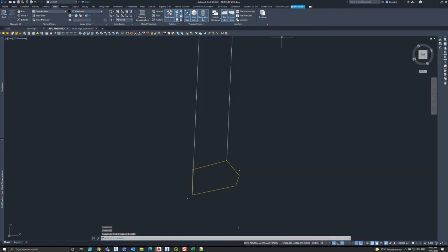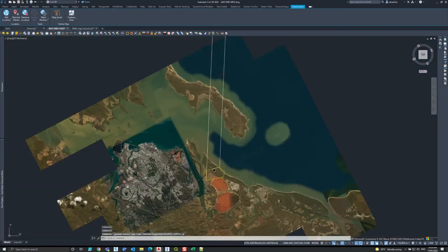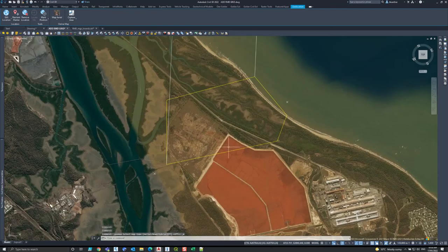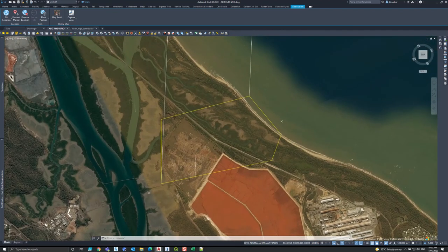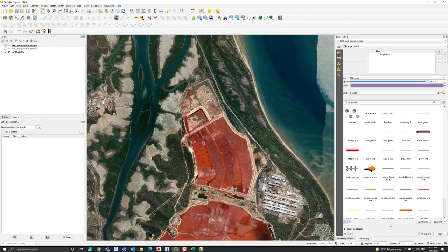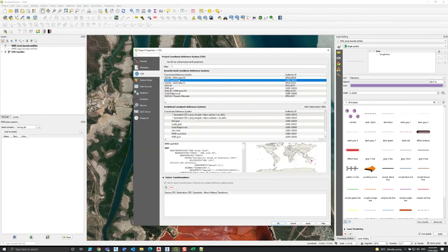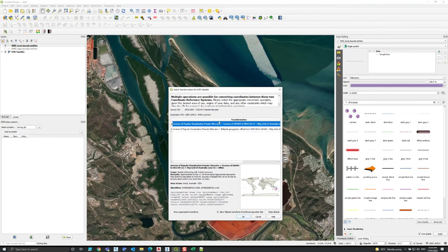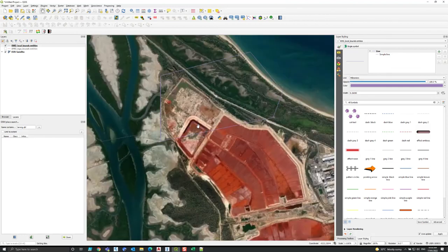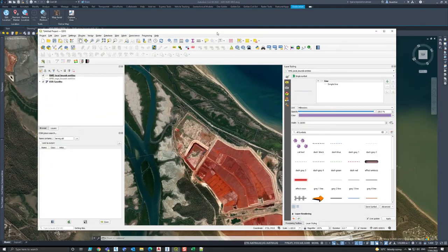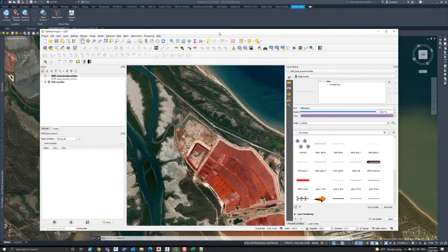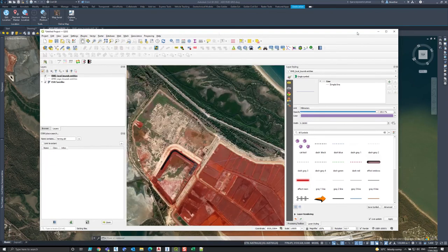So that's the local grid, and actually it only does it in one view too. Let's just change to single view. It doesn't like that. There we go, done. So that's our data in local grid, and we can see it's cutting across that corner nicely, lining up with the imagery the same way it was in QGIS. Let's switch back to RMD local grid. Agree to the transformation. It's just letting you know that's the transformation it needs to do. Different imagery than in QGIS, but nonetheless, same. I think this is using the Bing image.